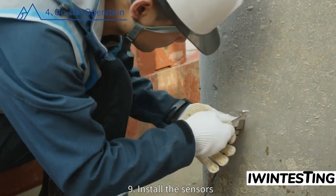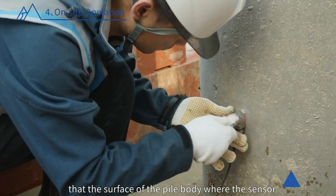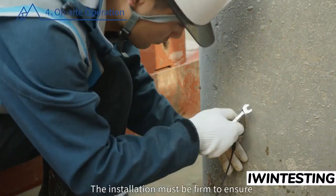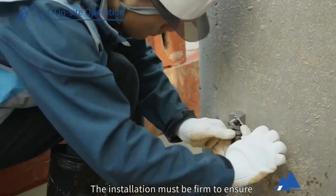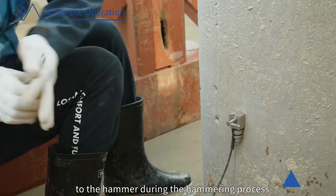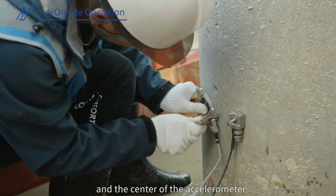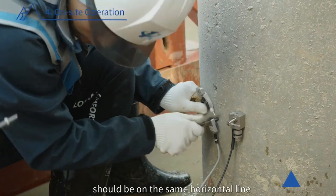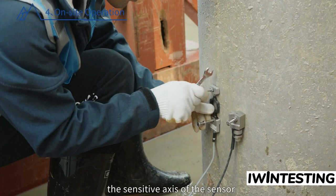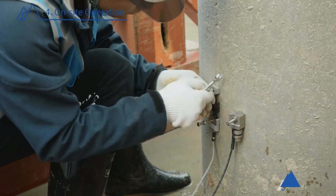9. Install the sensors. When installing, it should be noted that the surface of the pile body where the sensor is installed should be flat. The installation must be firm to ensure that the sensor does not slide relative to the pile during the hammering process. The center of the strain transducer and the center of the accelerometer should be on the same horizontal line. The sensitive axis of the sensor should be parallel to the central axis of the pile.